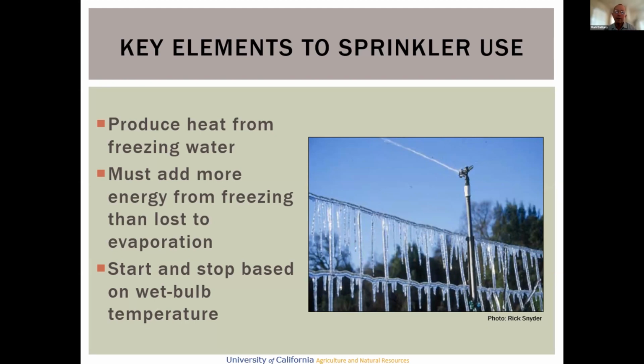So we have to make sure that that wet bulb temperature, when we turn this on, is above our critical damage temperature. If we wait too late and turn on the water, the temperature can drop to below our damage temperature, and then we end up causing more damage than we would have if we didn't turn it on. So it's really important to understand that.